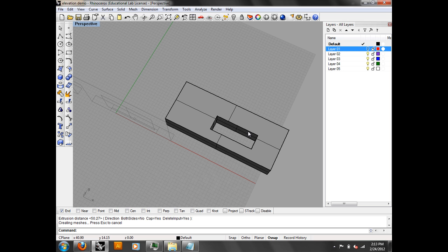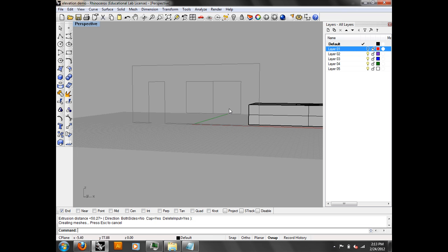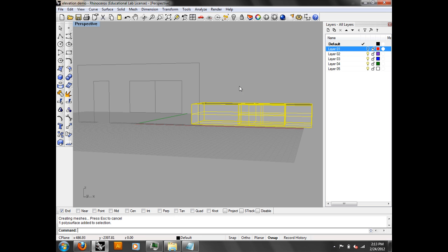You have the shapes. So you could say, well, I've got these CAD files, so I just extrude the elevation and I'm done. But there are things that can go wrong with that. First of all, your CAD files by and large are probably not that clean. You probably didn't join all the lines together as polylines. There are probably lines left over from different operations. There may be two lines hiding in the same place as a line. There may be a half line inside of a whole line. You don't know what's going to happen in there.